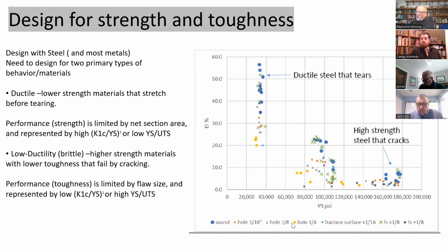So these are drilled round holes that are more severe than the porosity we find in the microstructure. So one of the questions design engineers often have is, yeah, a drilled hole isn't bad, but maybe that thing in the porosity acts like a crack. And so Stosey actually had us drill the holes to show that drilled holes were at least as bad as the porosity we have. So they're not cracks. They just are features that reduce the cross section.